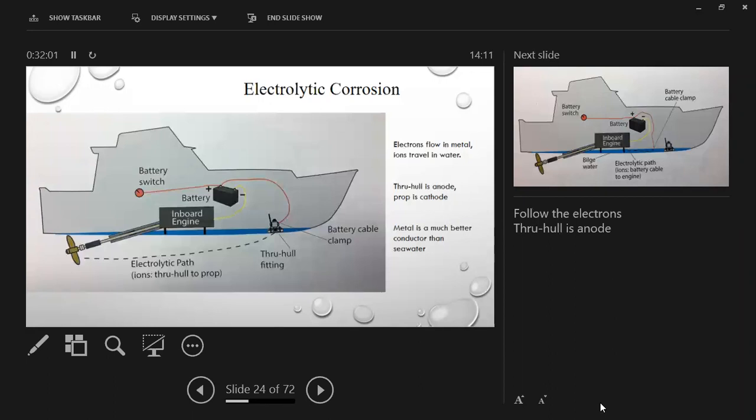Yes? Years ago in Baltimore, I looked at a big sailboat that had sunk. And this is exactly what happened, what you're talking about. Of course, the zinc was gone. Yeah. And over the course of about 4 days, it ate the through hulls out of the boat. And there was nothing left of it. And that's a bonding system. That's why I've always been kind of against requiring bonding systems, because in this case, this boat would not have sunk without a bonding system. ABYC.